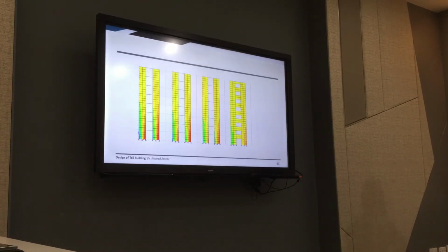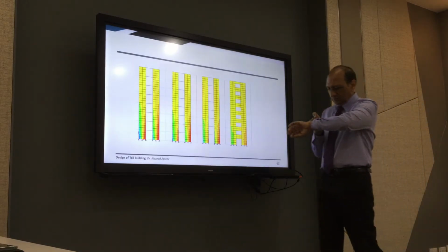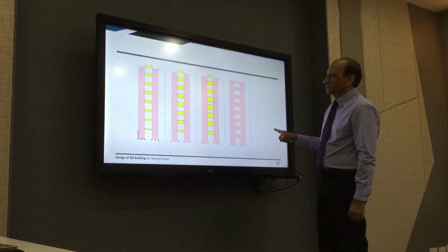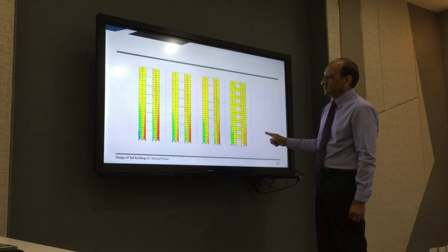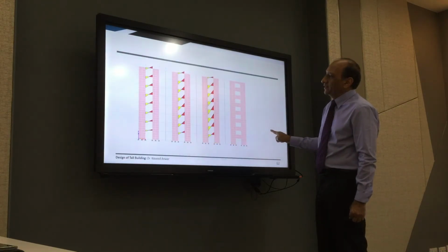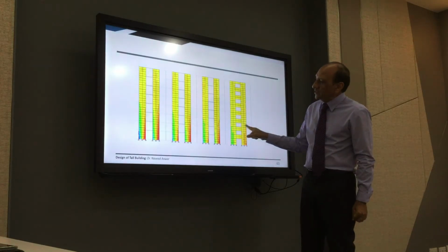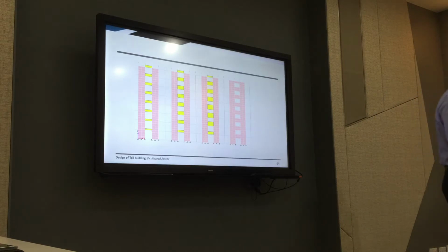And that is much more efficient than bending. Yes? No? And that is the shear in those links. That is the bending moment in those links. So normally we design the bending moment to be limited in such a way that this shear does not exceed the shear capacity. Right?